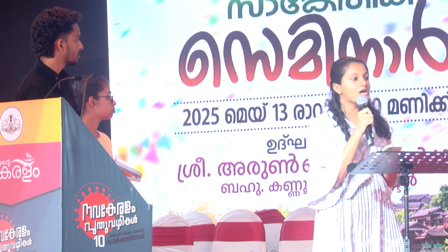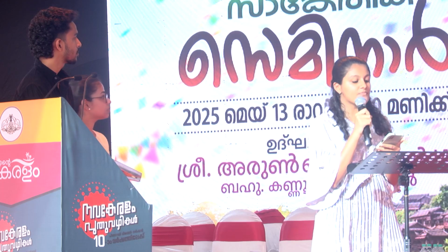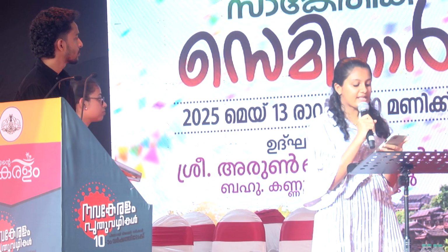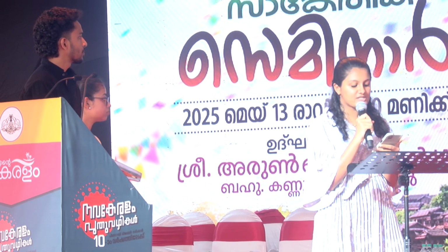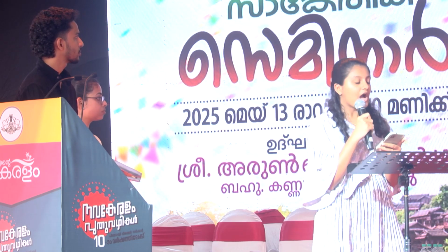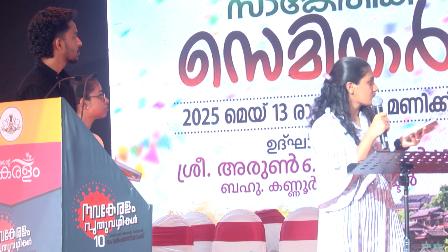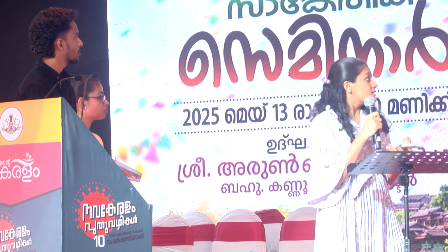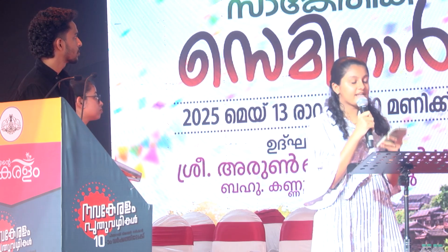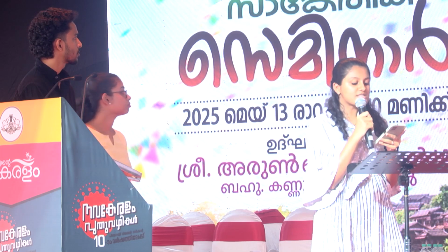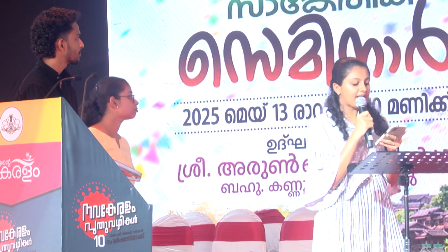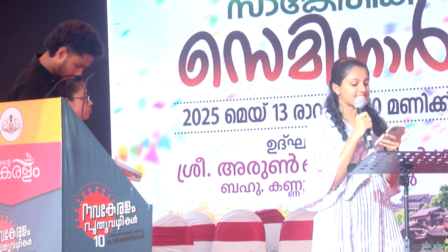Our objectives are to find the characteristics of wastewater, preparation of adsorbent, to find the effect of adsorbent dosage, to find the effect of pH, to find the effect of contact time, to find the concentration of contaminants after treatment. Our literature reviews are properties of an adsorbent. It has a high surface area, porosity and pore size distribution, affinity for adsorbate, thermal and chemical stability, regenerability and selectivity.